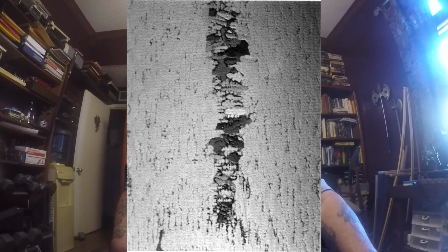But keep in mind that not everything is just a wheel. You might be making a valve. You might be making a pump body. Things that are going to have pressure generated inside that casting. If you've got voids like this inside the wall of your casting, when you get that tested and the casting starts springing a leak, it's going to be rejected, and you're going to have to make that thing all over again. So when you're making something, keep that in mind.